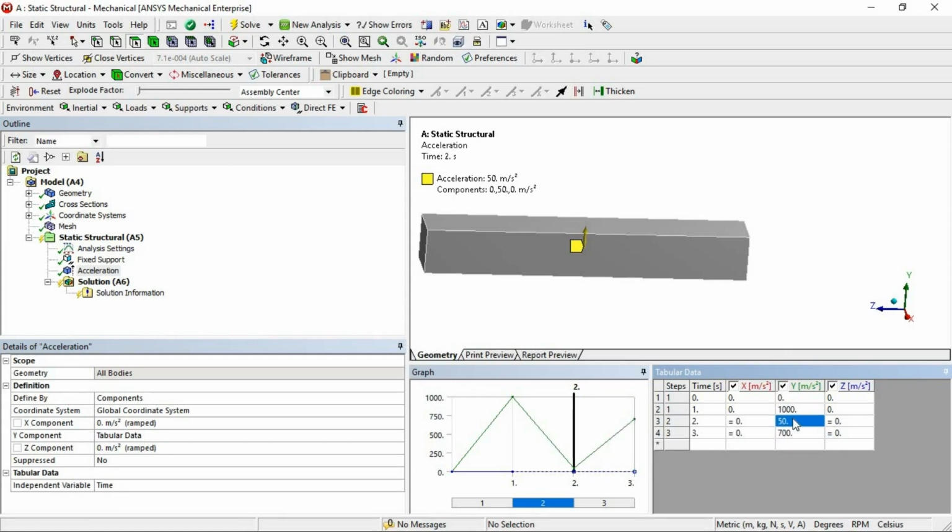The purpose of doing this is that there might be chances you will have inputs like this, the loading condition. So you will find there is a change in the deformation pattern from 1000 to 50. So the graphics may sometimes be scattered. So in that case you should avoid doing a multi-step simulation if your purpose is to record animation plots.